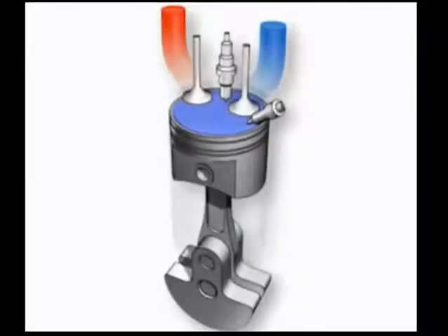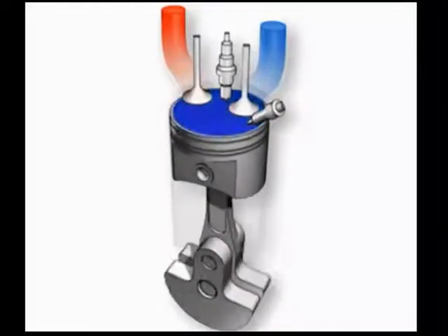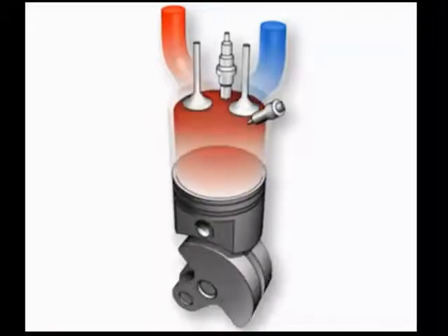Mode of operation of a naturally aspirated engine. In order to understand how to optimize the output of an engine, we shall first consider the mode of operation of an internal combustion engine. Most passenger cars and commercial vehicles are driven today by four-stroke piston engines. In this case, one work cycle comprises 4 strokes which run during 2 turns of the crankshaft.